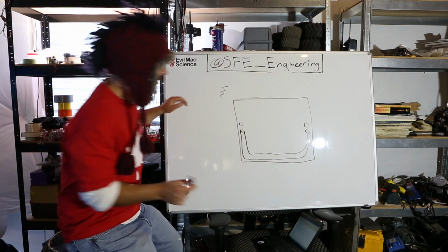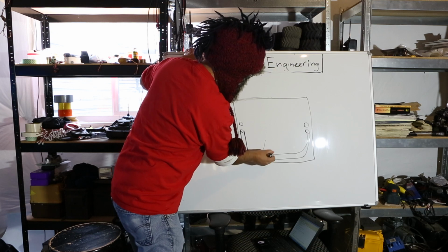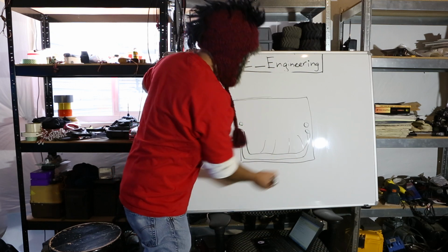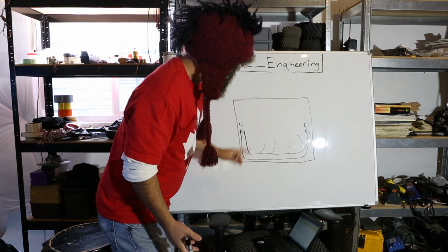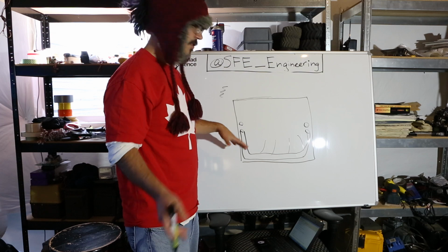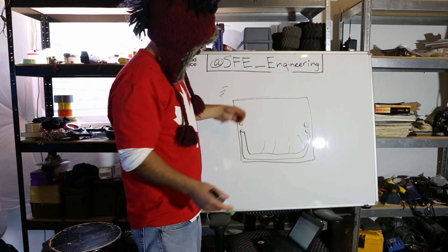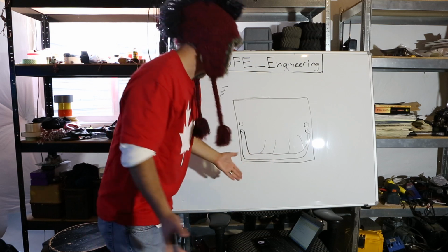Now, if you're not daisy chaining, and you're feeding circuit sections like this, that's kind of goofy. I would not do this, and the reason is because I prefer to have a star configuration. Although you could argue that there's so much copper here that it's virtually a star configuration, but it's not.